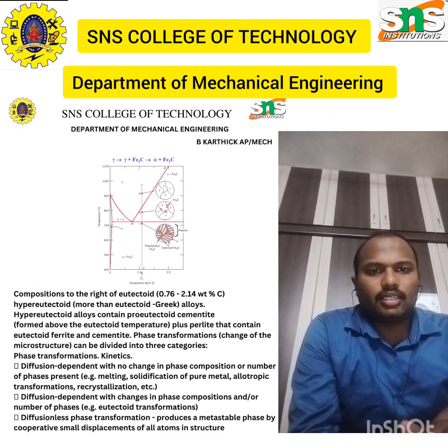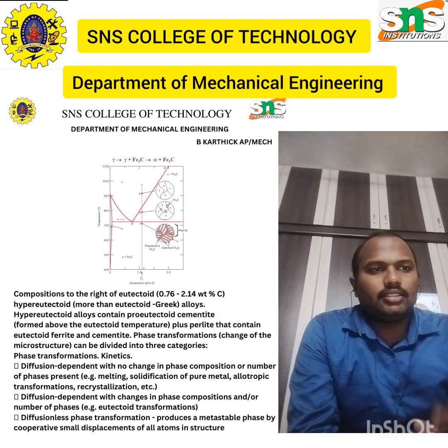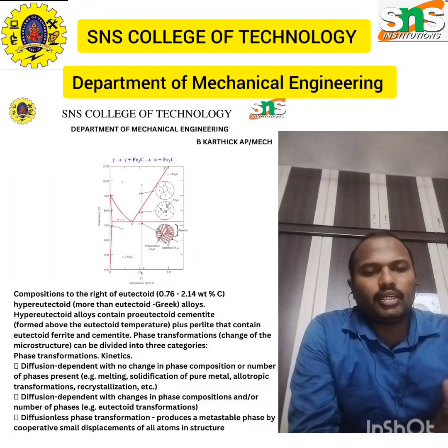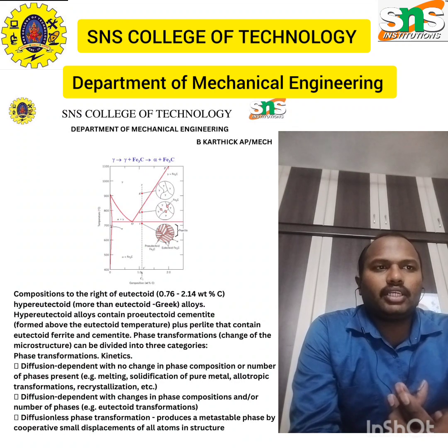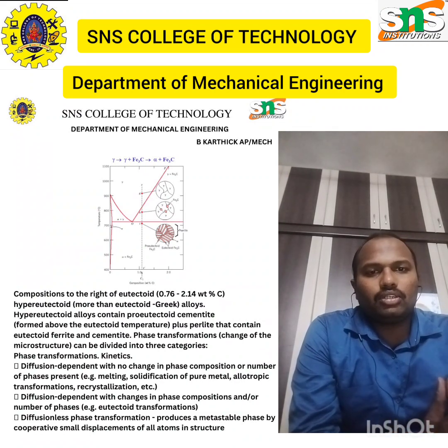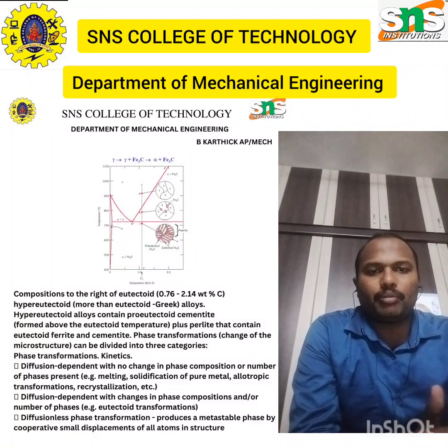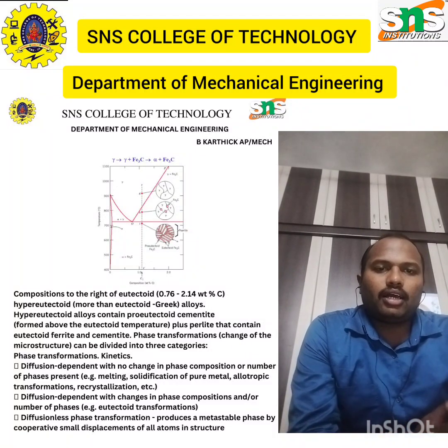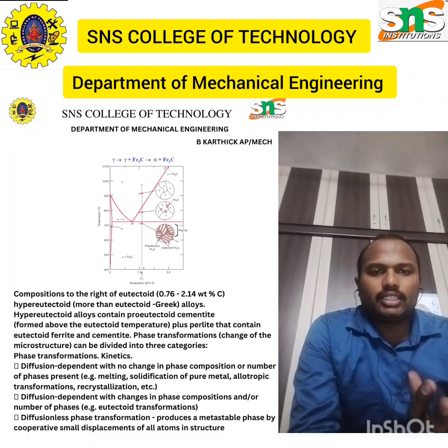In the last lecture series of mine, I have spoken about the iron carbon phase diagram. In this lecture series, I am going to speak about an in-depth version of the iron carbon phase diagram, or in other ways we can say I am going to particularly stick to the eutectoid invariant reaction, where one solid upon cooling gives two different solids of different properties and different parameters, or else we can say the two solids on heating give a third solid which has different properties from the first two, right?